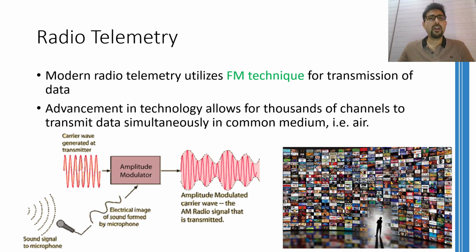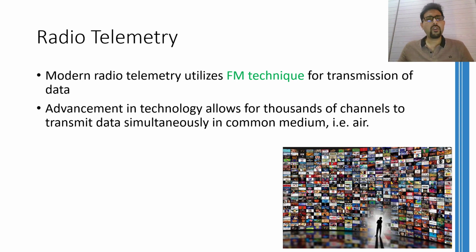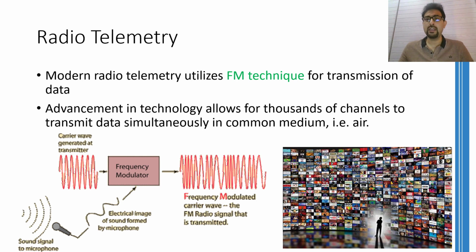The modulating signal rides on the carrier signal just like as you ride on public transport and get off at your destination. Similarly, the modulating signal will leave the carrier signal at the destination and the device that causes the modulating signal to get off the carrier ride is called the demodulator. On the contrary, if the modulating signal is doing nothing to the amplitude of the carrier signal, but it is changing the frequency of the carrier signal, then this thing is called frequency modulation. Now, the frequency of the carrier signal is dependent on the modulating signal.